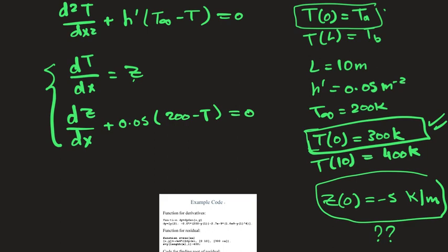Is anyone practicing or doing anything? So how do we solve this in MATLAB? Remember, we do this in two steps, right? First, we define the functions, and then we pass them to a solver along with the initial conditions. Just to follow the same approach, we will use the ODE45 solver. That's the function that we call to solve, right?